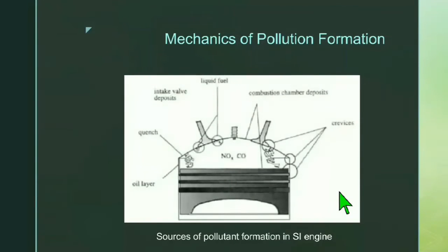Mechanics of pollution formation. Sources of pollutant formation in an SI engine: oil layer, quench, intake valve deposits, liquid fuel, combustion chamber deposits, crevices, and here is NOx, CO.